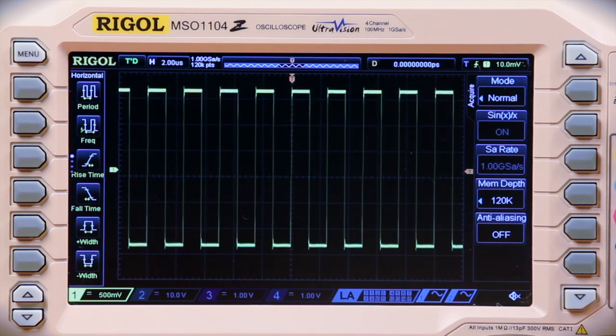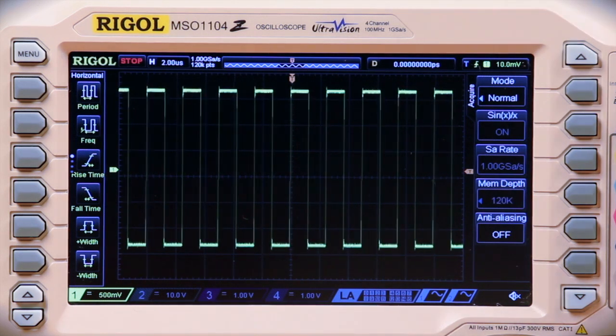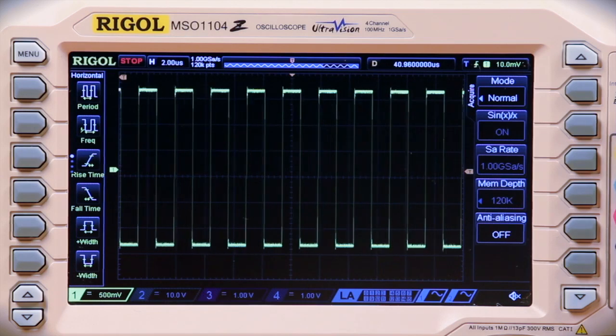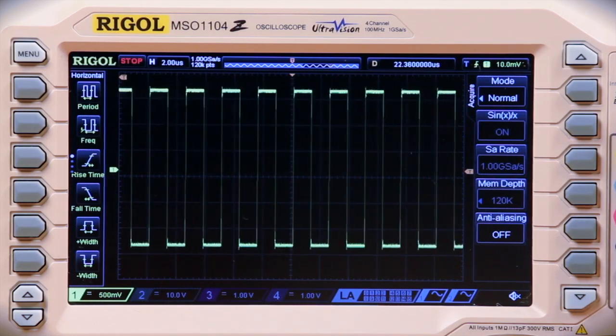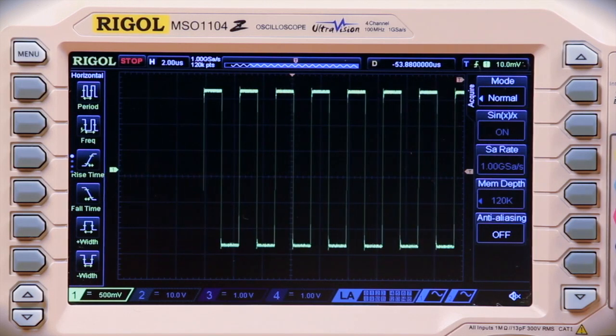Once you stop capturing waveforms, you can then move to view parts of the waveform that are originally off the screen. Triggering is a reference point for how we compare and evaluate signals. Understanding the basic concepts and different methods of triggering makes signal analysis more effective.